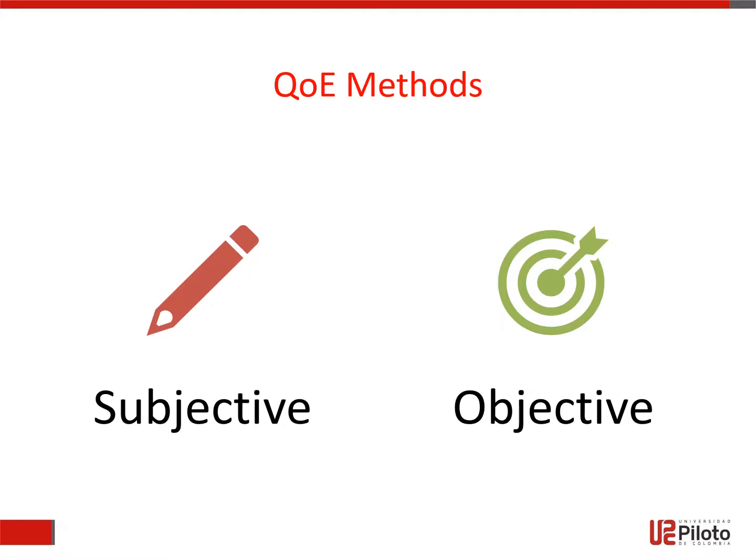The principal objective quality assessment is to estimate subjective quality solely from objective quality measures or indices. It employs statistical models, media layer, parametric, bitstream layer, neural, etc., for quality prediction. And this method depends on validating the objective estimation model against unknown subjective databases. Three major model approaches have been identified: the full reference, no reference, and reduced reference.